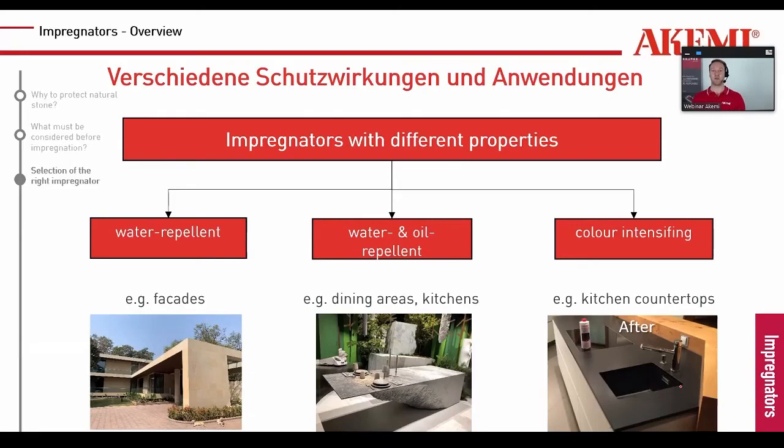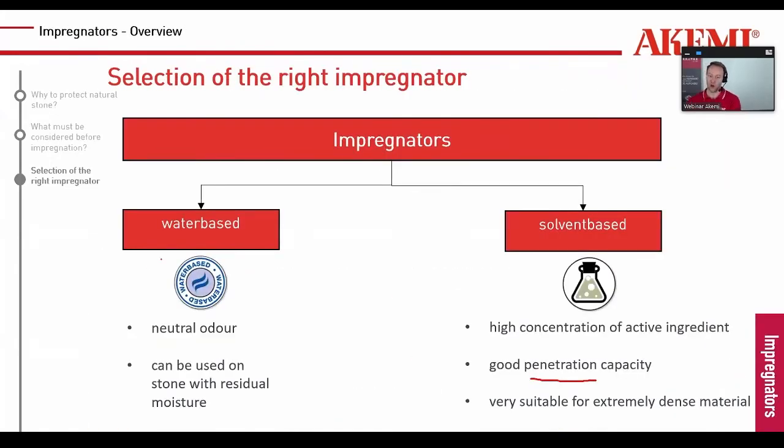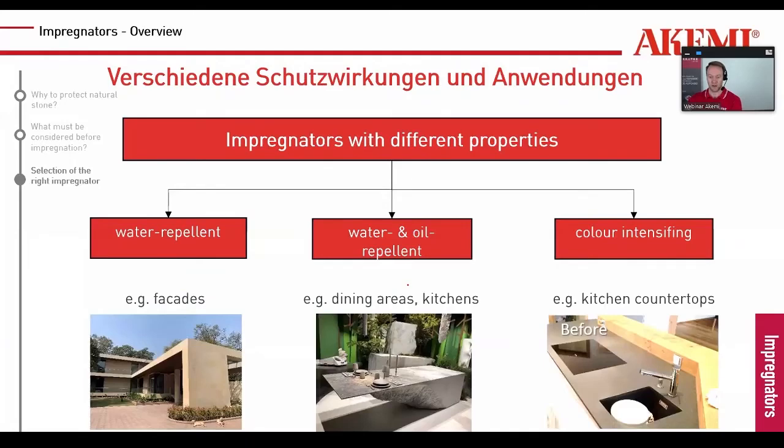So if the stone is still wet or you're not sure if your stone is completely dry, you always have to go for a water-based product. Or you have to make sure that you dry your stone properly. You put a radiator or a heater in, or you wait some days or weeks until your stone is dry. Usually, as I said, you get the deeper penetration, especially with dense material, with a solvent-based product, and probably also the longer lifespan of the sealer. So here you should consider drying the material first in a proper way and then treating it.